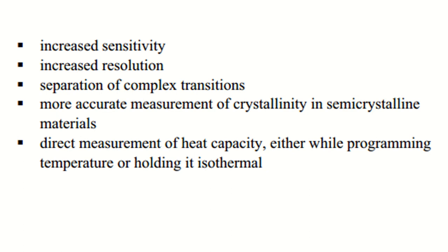It measures the heat capacity component as well as the total, and obtains the kinetic component from the difference. That is the huge difference between simple traditional DSC and modulated DSC. Separation of complex transitions into specific components greatly improves interpretation of results.